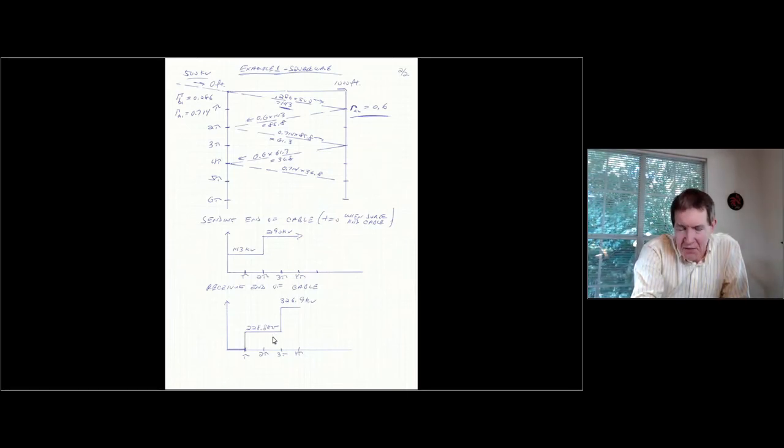which is 228.8 kV here. Then it travels back toward the source side, reflects, comes back down here, and has another reflection. To get this next change at the load side, I need to add 143 plus 85.8 plus 61.3 plus 36.8, which adds up to 326.9.